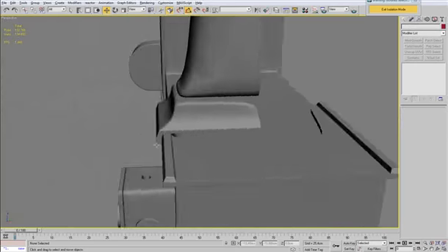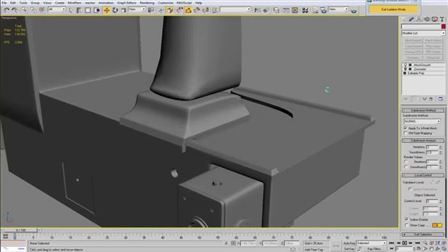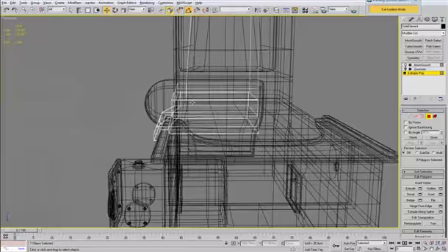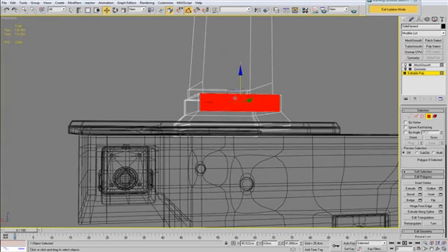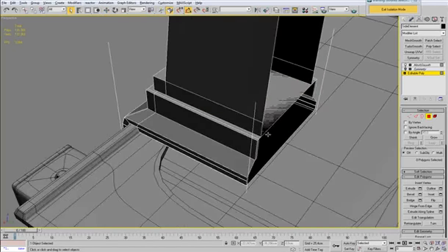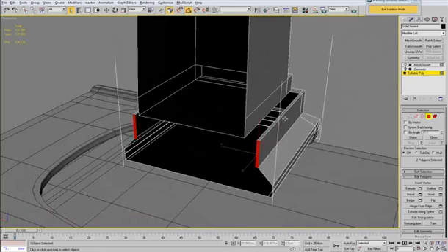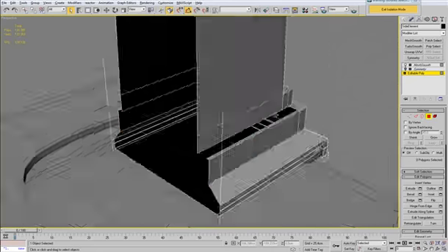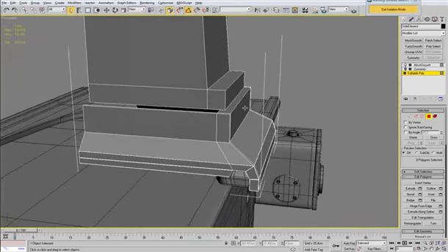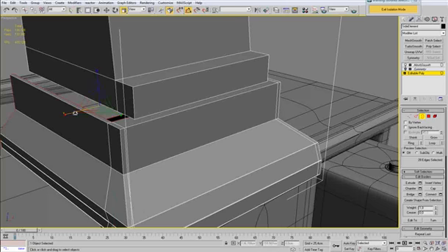By pasting it as instance, you save yourself a lot of trouble, because whenever you need to correct the values of the modifier, you do it once, and that takes care of every single part that has that modifier. It's easier than going through all the parts one by one. So I recommend using instance modifiers.